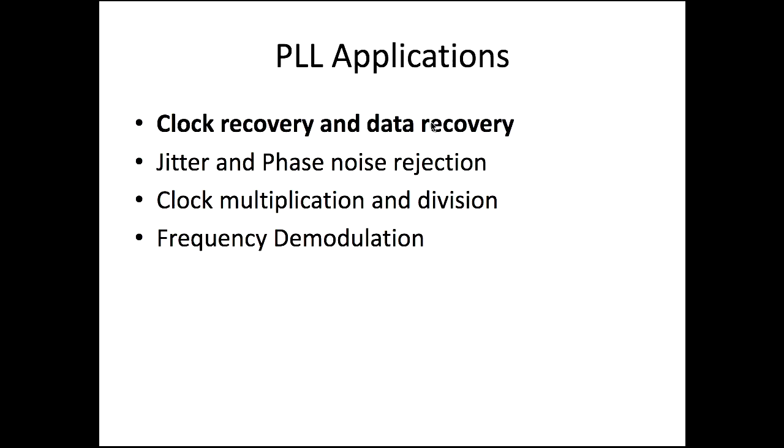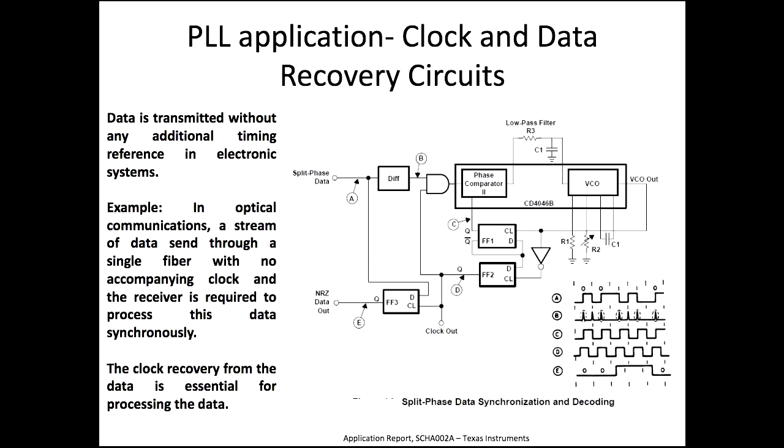But clock recovery and data recovery, everybody should be knowing as a system engineer. Why we need PLL? You should know we can use the PLL for clock multiplication and division. We can do frequency demodulation. So why I said the other one is complicated is the following.